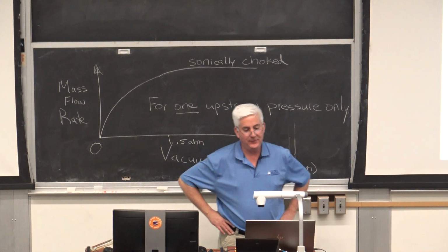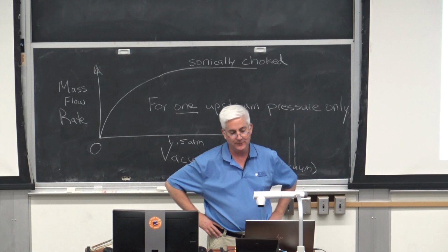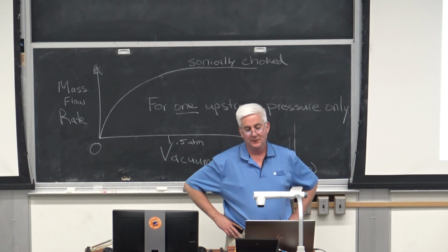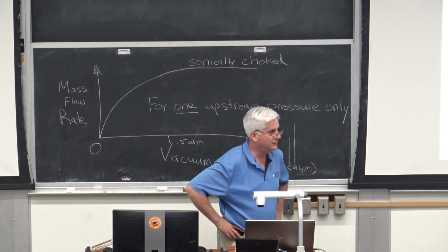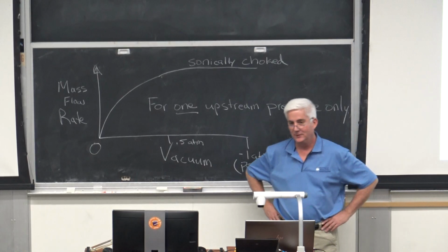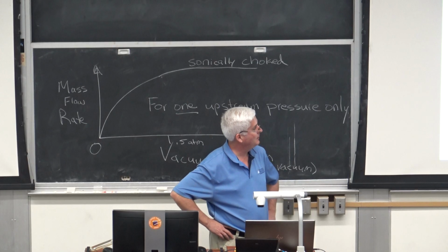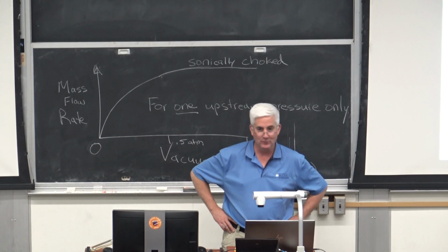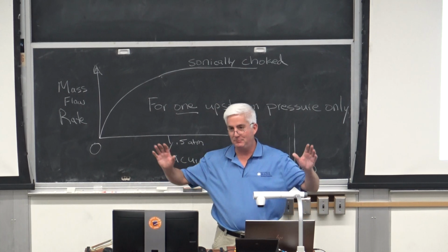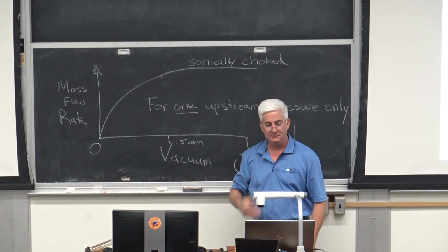The melting point of fused quartz, which is the highest temperature clear substance that I know of, maybe sapphire is a little bit higher, is going to melt around 2,930 F. So Mav's got a sunroof long before he ever hits Mach 10. It's going to get a bit breezy in that cockpit. Not to mention really stinking hot. So if you ever see these pictures of the SR-72 Darkstar and it's got a windshield, wrong.